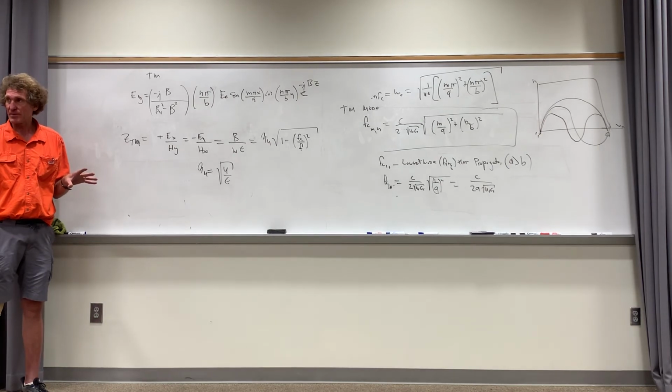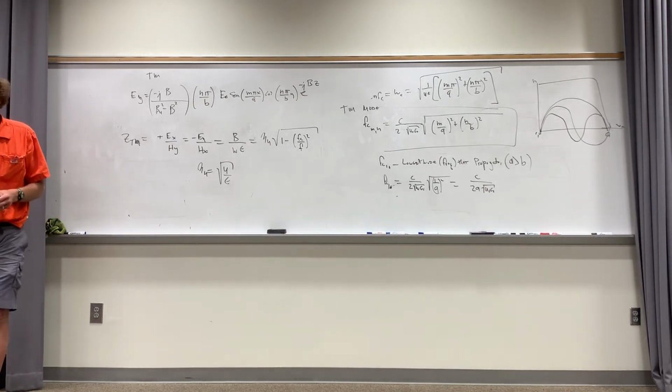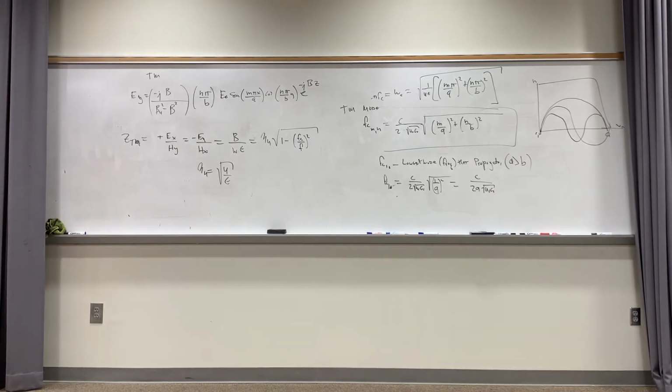I'll get to what happens if you try to drive a waveguide at a frequency lower than the cutoff frequency. It gets into a mode called an evanescent mode, which is where the energy rapidly decays and doesn't penetrate at all. But that's for another day and another time.